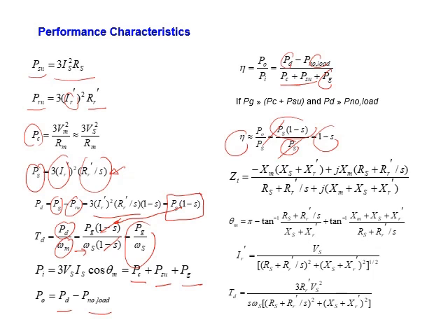Now, definitely for the electrical elements, the total impedance we have at the end is the primary in parallel with the core losses, in series with the secondary. But if we go to the approximate circuit where the core loss is shifted to the supply, then primary and secondary are in series, in parallel with the core losses. Their impedance and phase shift are represented by this one.